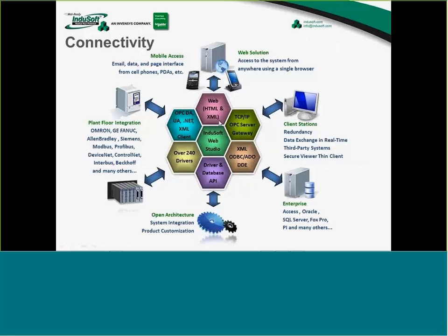And then we also have some toolkits that will let you get at drivers and other ways to get into our tag database. Some interesting strengths about this, the way that this diagram is showing our product, is that we can use InduSoft Web Studio not only to have multiple protocols talking over our built-in drivers and maybe sharing information from one brand of PLC to another brand of PLC, but we could also get information from a driver, from a PLC, and maybe put it into a different PLC via OPC, or get information from OPC and send it to a database. And notice that this is not one direction, this is bidirectional. We can get information from a database and send it to an OPC-enabled device. So lots of different ways to get communication in and out of InduSoft and share that information as it relates to this webinar with OPC UA.